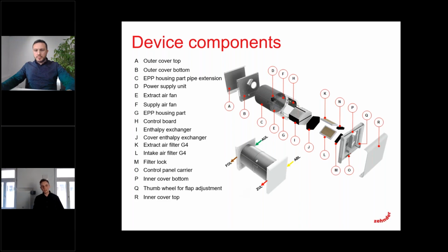I want to point out here that people sometimes think that there is a recirculation, but due to the orientation to the side, we make use of the Coanda effect. The air streams along a wall and then it spreads into the apartment. So there's no recirculation. And the same effect is used at the outside, so that there's no recirculation from the exhaust to the incoming air.